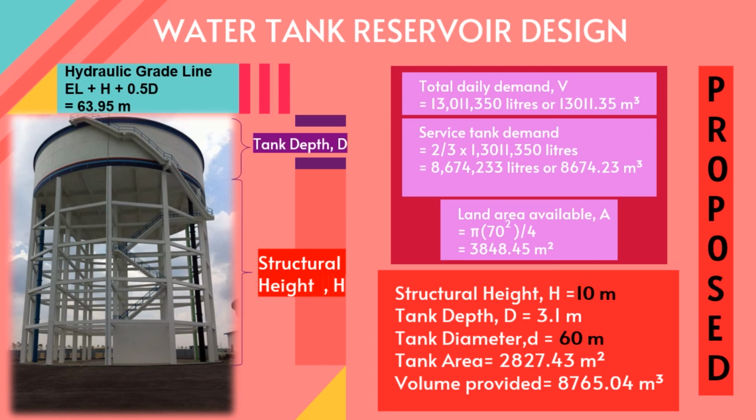In addition, my water tank is designed to be built as a concrete water tank. I chose concrete because it is available in every size and capacity. It is also long-lasting with maximum strength due to reinforced steel in the concrete. More than that, it has excellent insulating properties, keeping the water cool. Even if there are some disadvantages such as cracks and leaks, there are solutions, which are a waterproofing seal for the inner surface of the concrete tank and polyurethane foam injection grouting to immediately stop the water from leaking if there are any.